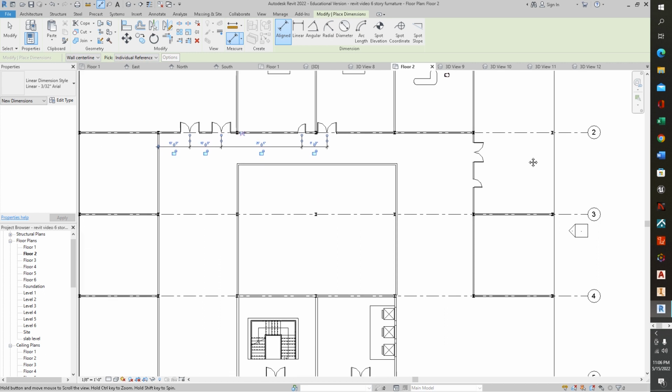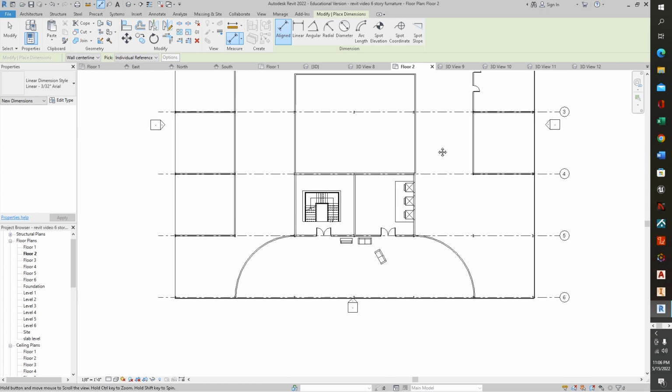So with that in mind, you're generally going to have a much larger piece of paper. Your 2 foot by 3 foot is pretty common practice. So you've got a lot of space to put your annotations in, so you don't have to worry as much. It's still nice to have them in a way that makes sense, but you can put a lot of different dimensions in there without having to worry about over dimensioning as easily as on a smaller drawing.